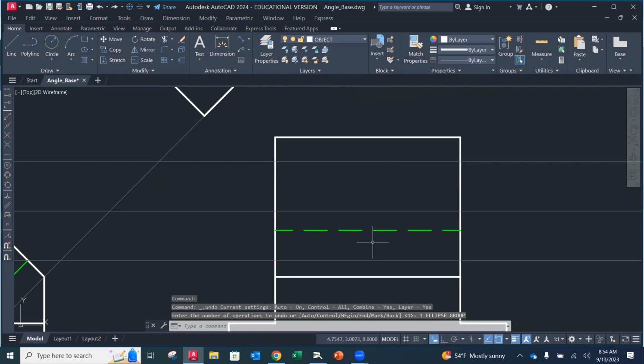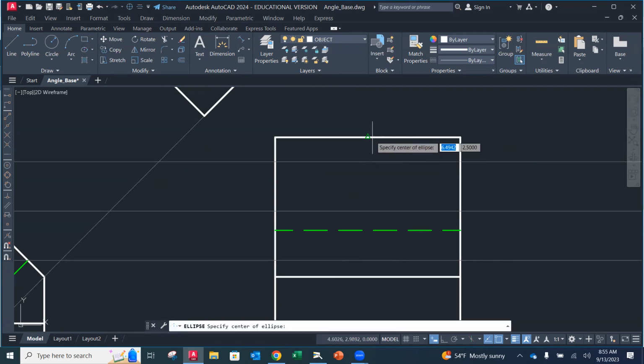So because I have my construction lines across here, and I have my show snap references. Do you have this in place already, Jake? Okay. We're going to be on our object line layer because it's a visible line. We're going to go to ellipse. We're going to find the midpoint of this rectangle here, and track it down to that second one. That's going to be the center of our ellipse.